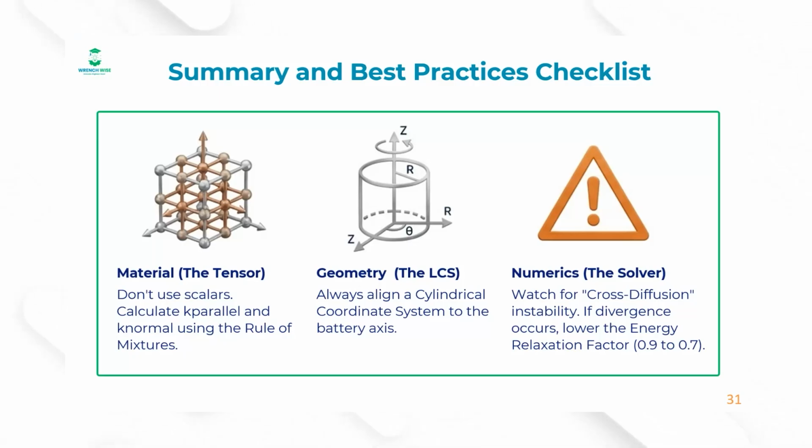And ultimately, if you are using the anisotropic model, there is always the cross diffusion instability. Just to clarify, even if your mesh is perfectly valid, with very good skewness and very good orthogonal values and so on, numerically and mathematically speaking, the high anisotropy ratios still behave like bad meshes, which will lead to cross-diffusion instability.